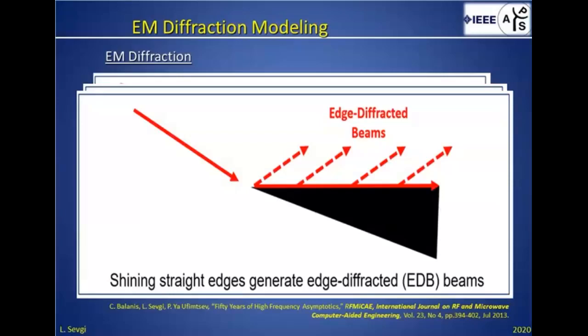In most communication links, for example for our cell phones, the antenna of our cell phone usually cannot see directly the antenna of the base station. So there is no direct wave and no reflections, but the communication link between your cell phone and the base station antenna is established because of the diffracted waves. Basically, diffraction establishes links in shadow regions.